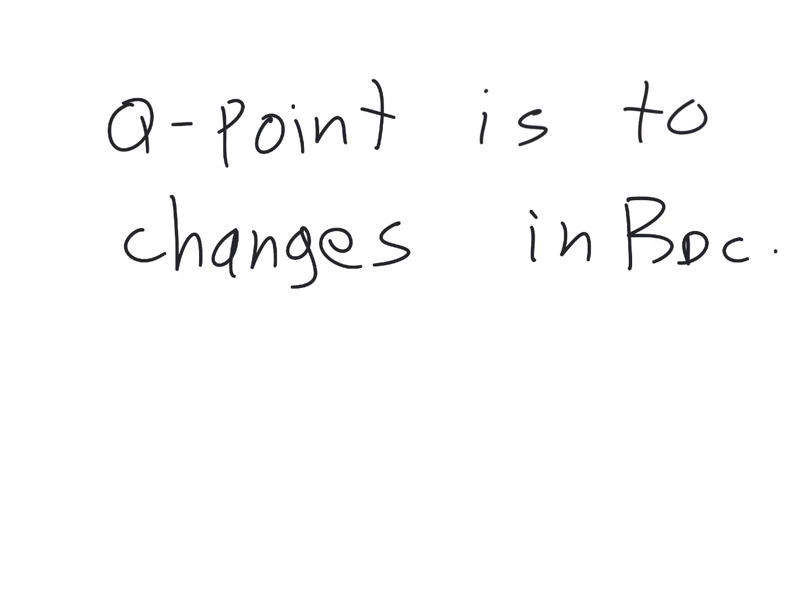So you need a biasing method that, for the most part, fixes the Q point at the desired point on the load line, irrespective of what the actual beta is. It's not perfect, but it's pretty close to perfect. It does a very good job at self-correcting itself if the beta changes.